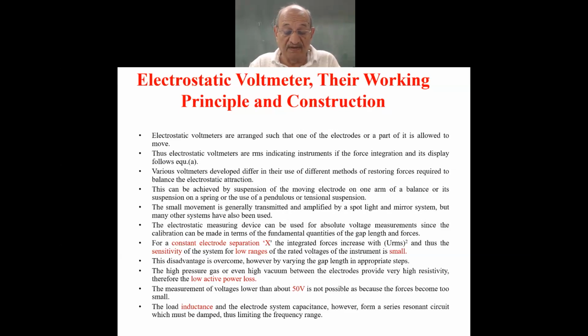The electrostatic measuring device can be used for absolute voltage measurement, when I said RMS voltage measurement, since the calibration can be made in terms of fundamental quantities of the gap length and forces.